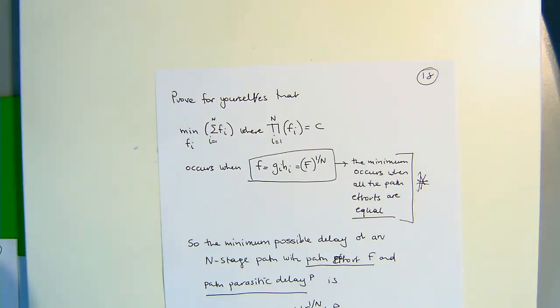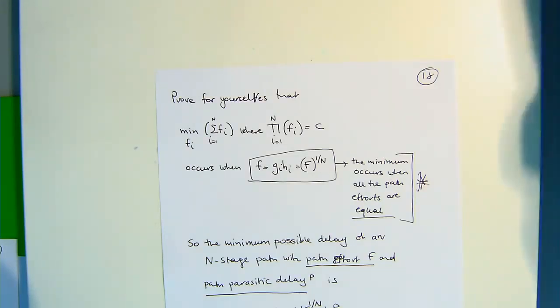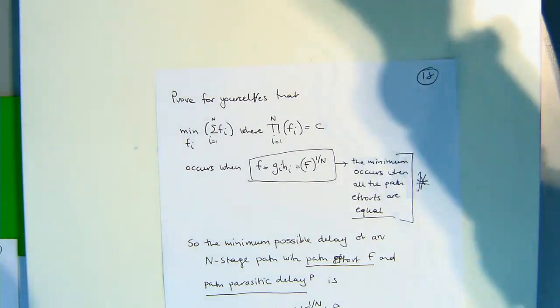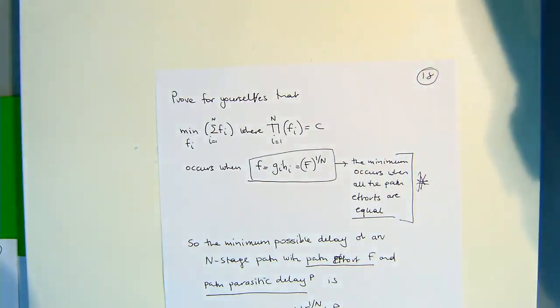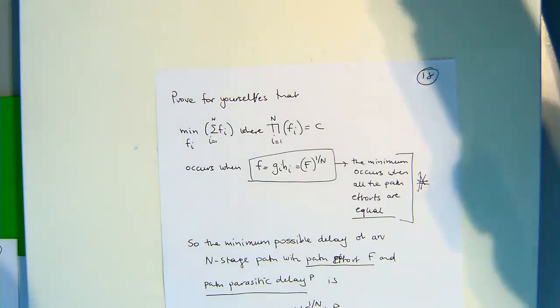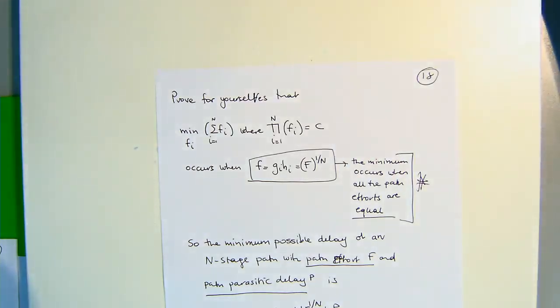I've got a logical function, and I've looked at that logical function, and I'm not going to put any XORs in there because I know that XORs are pretty bad. But what I've got is the function. The next thing is how am I going to scale this? How am I going to size each of these components such that I have the minimum delay? That's always an important question, right? Because you want to remember, it's high-speed electronics. Everything's about making it high speed, right? So the question is, how do we make that delay as small as possible?